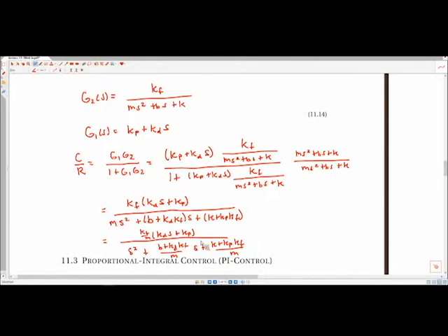So it has damping in the system. If it didn't have damping, it wouldn't slow down. But we expect something like this to slow down eventually. So the system naturally has damping in it, and that's reflected in this term right here. KF we can't change. That's part of the amplifier and motor system. But we can change in a virtual environment just by changing a few lines of code.